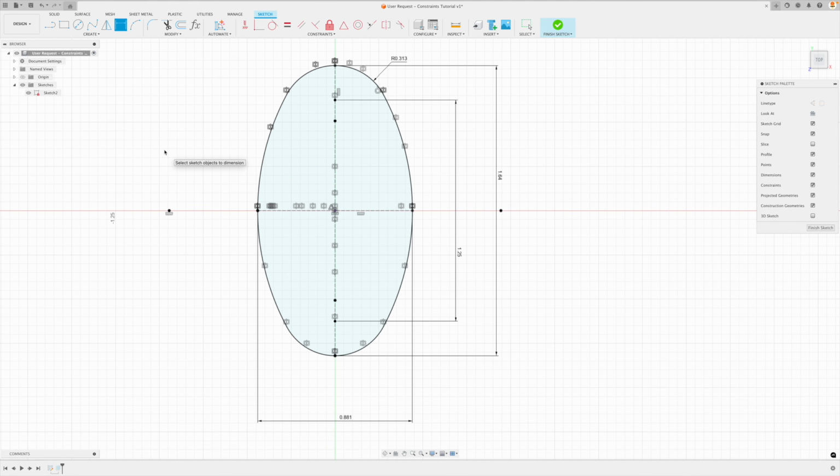If it isn't, that's when we'll see a special note, or we'll see another dimension saying that it's going to be a certain distance off of the center line. But we can see on the drawing, we can assume that those holes, the counterbore holes, are in line with our y-axis on our sketch plane. So there we go. Let's go finish sketch.